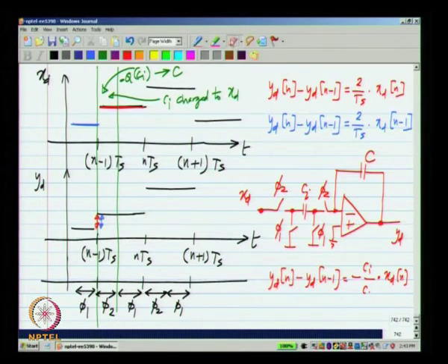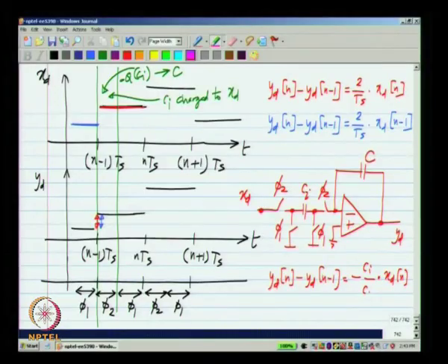You see that it very much looks like the first one except for this minus sign. Now, if you are implementing the circuit in a fully differential manner, which is the most common way of implementing these filters, there is no problem, you simply swap the wires and then you get the negative voltage. So, this is a circuit that implements this backward Euler integration.